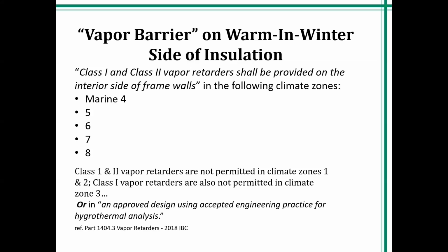Someone determined, well, let's use an ice and water type of material. There's like a 40 mil SBS rubberized asphalt material. To me, I think a more expensive option than using the building wrap, which would have been a lot less costly. So not only did they have a vapor retarding air barrier on the cold and winter side of the insulation, again, no CI here, and they also applied their 6 mil poly vapor barrier, again, I'll use that old term, behind the interior drywall.